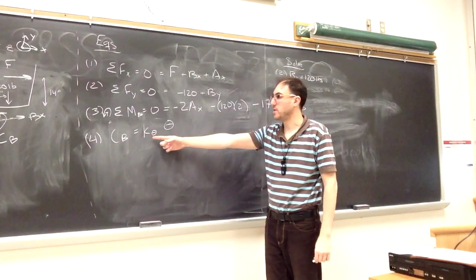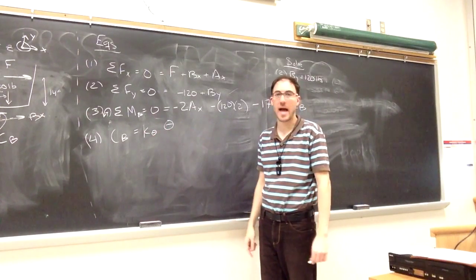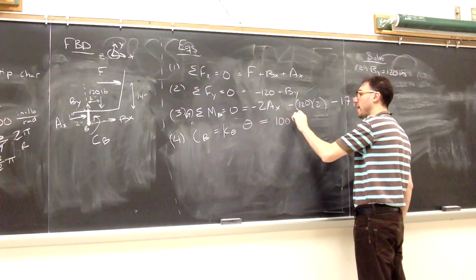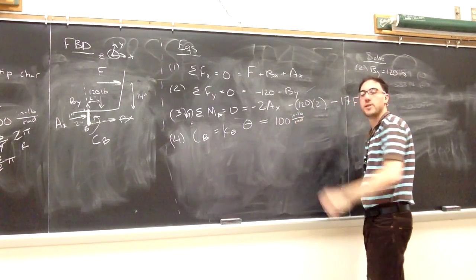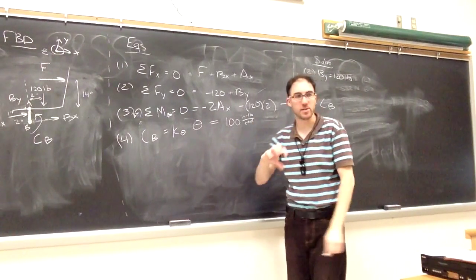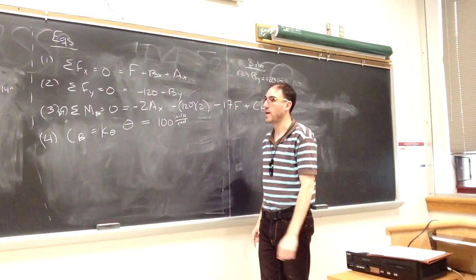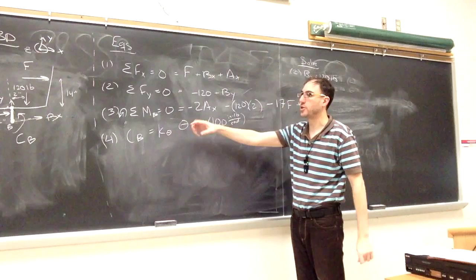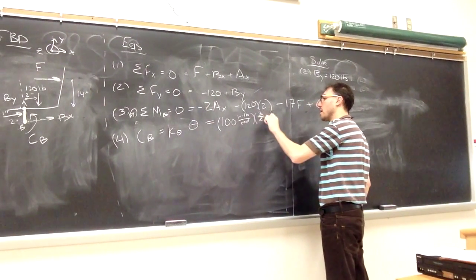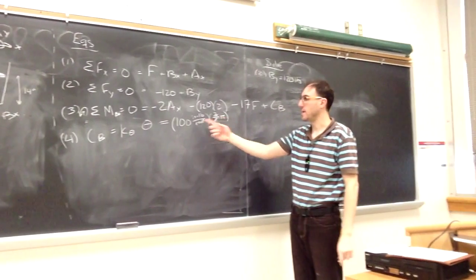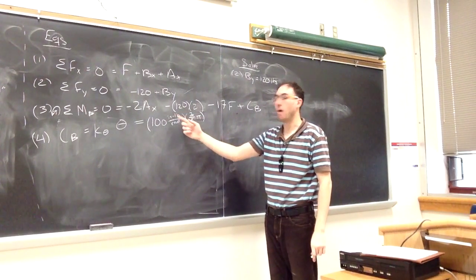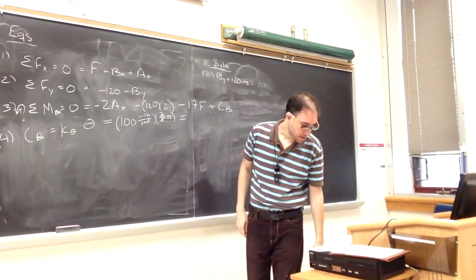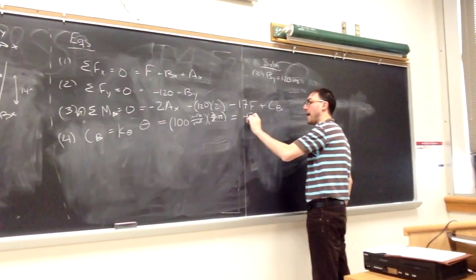This we were given in inch-pounds per radian, which means that the angle has to agree with that. So we were given that it has a spring constant of 100 inch-pounds per radian. And when the chair is vertical, that spring has been deformed 3/4 of a turn, or 3/2 pi radians, from where it usually wants to be. So that angular deformation is 3/2 pi. Again, radians and radians, so our result, the moment, will be measured in inch-pounds. So the couple we get is 471 inch-pounds.